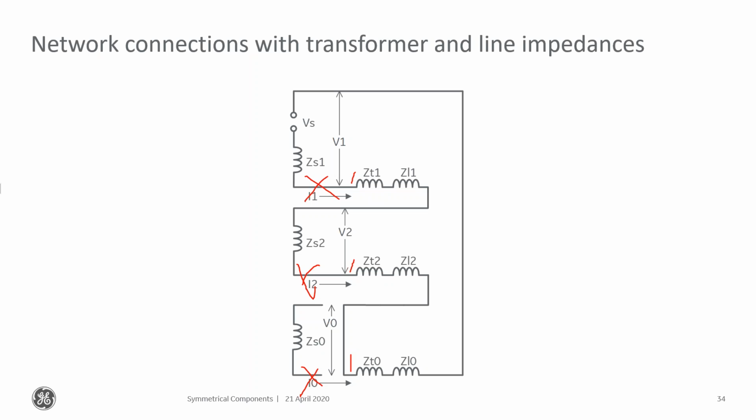And I can see the negative sequence component of that fault, and I can see the positive sequence component of that fault on the H side of that transformer where I drew my X. But what I can't see is those zero sequence components, which are sitting right there. The reason I can't see them is because that transformer blocks that.